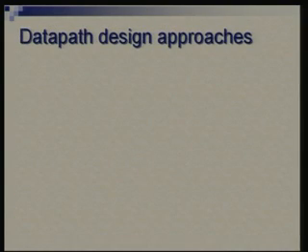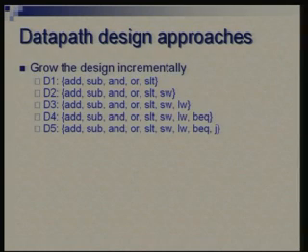So let us compare the two approaches which I am talking of. One approach we followed in the last lecture and another one we will follow now. What we did yesterday was that we began with one design, let us call that D1, where we looked at 5 instructions which belong to one particular group, namely the arithmetic logic group. We augmented that design by including store instruction. We expanded it further by including the load instruction. Then we added on BEQ instruction, and then finally we threw in J instruction. So that is how, starting with a very simple design, we gradually built up a more and more involved design, and this process actually can be continued.